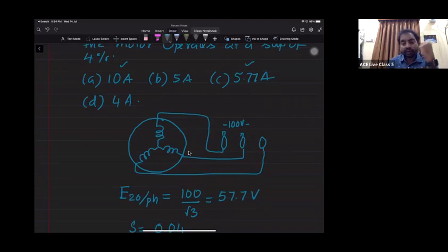Can you give the answer? Windings are designed based on phase currents. Line current is maximum. Resistance is per phase. Everything is divided per phase. Equivalent circuit is per phase. Resistance is always per phase. We want to calculate only phase. Winding impedance is per phase. The system is balanced. Everything is taken per phase.